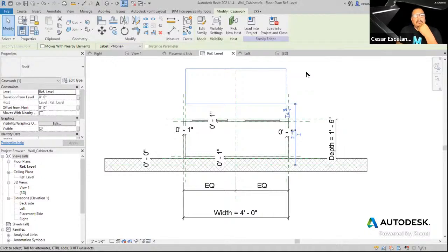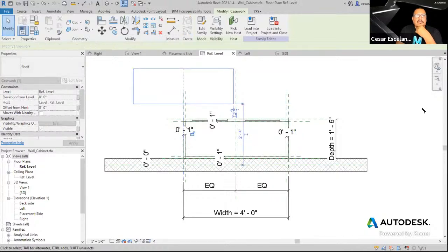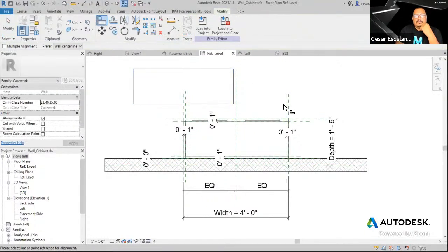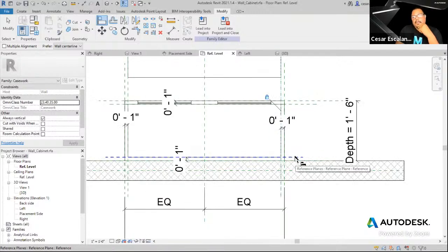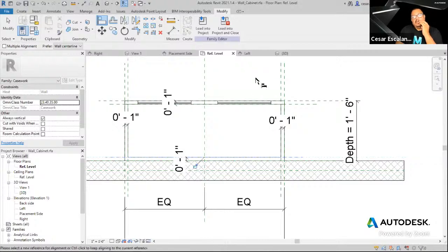And I believe it's located in the right place, horizontally and vertically. I'm going to check that, but I need to lock it in X, Y, and Z. So I'm going to align it where it needs to be. Let's fix it in the right direction. Again, you can pick any reference plane. I'm just picking the right one. So align to this reference plane, the face of the shelf, and lock it. Align to the back face of the cabinet, the shelf face, and lock it.